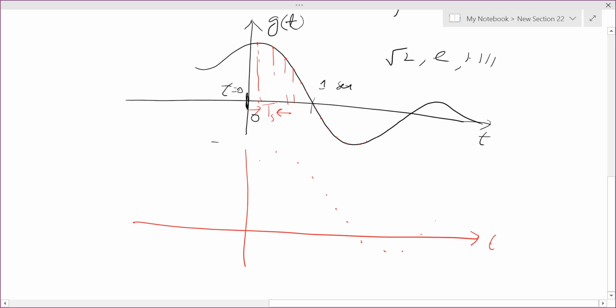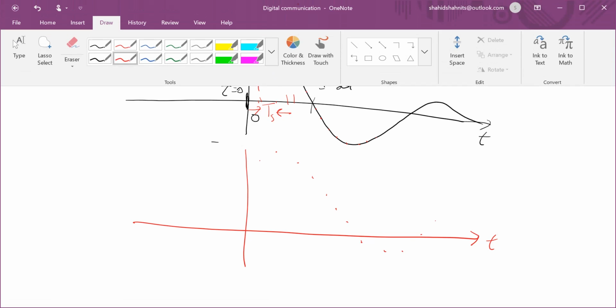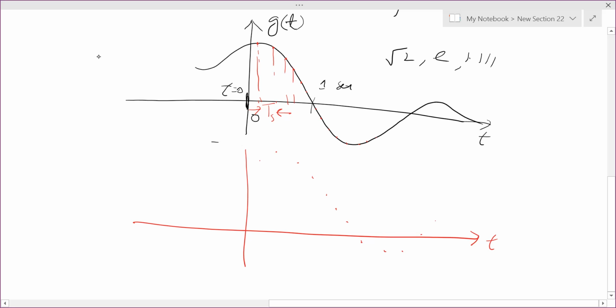Now the question is, if you transmit this signal, the sampled one, from these samples, will we be able to recover the original signal? Let's see a mathematical way of recovering the original signal. You may say that I will join these points, extrapolation you can say. So I can join these points via straight lines. Okay, so this somehow resembles the original signal, but since these are straight lines, there is some error also. Now, how to reduce the error?